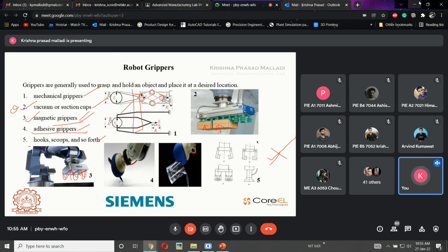And adhesive grippers. Adhesive grippers are like glue, as well as some soft grippers, whereby we can pick components like this. See, if it is a glass-like thing, where the application prefers no vacuum, I mean no pneumatic either, at that application, special applications, we go for the adhesive grippers, where somewhat special applications are needed for this adhesive.